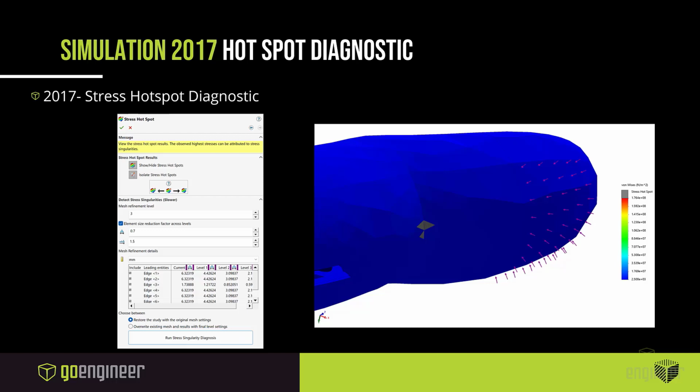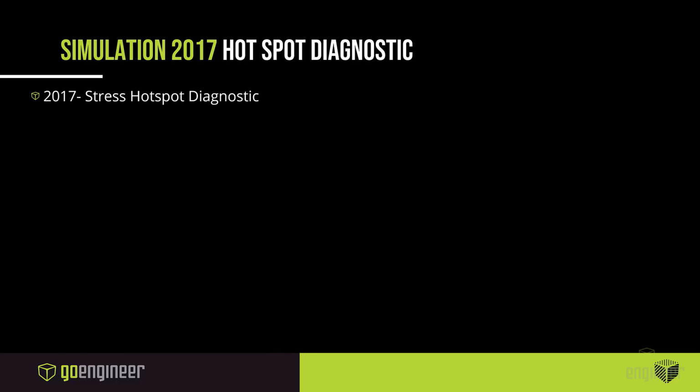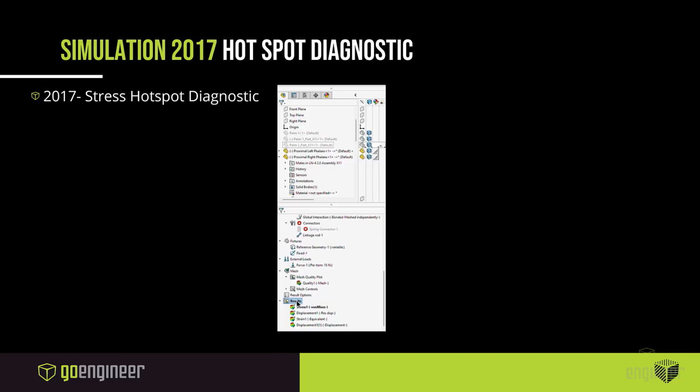We are going to be building a mesh over a line or a vertex, and there's no real way for us to separate the mesh in an area, so it's just going to be over a line or a dot, and that's pretty much what it does and how it works. This is a big issue for designers and engineers because we need to have reliable data. And we can't have that if we have hotspots everywhere. If we have artifacts from our mesh, this is going to interfere with how we interpret our results and how we present this to our team.